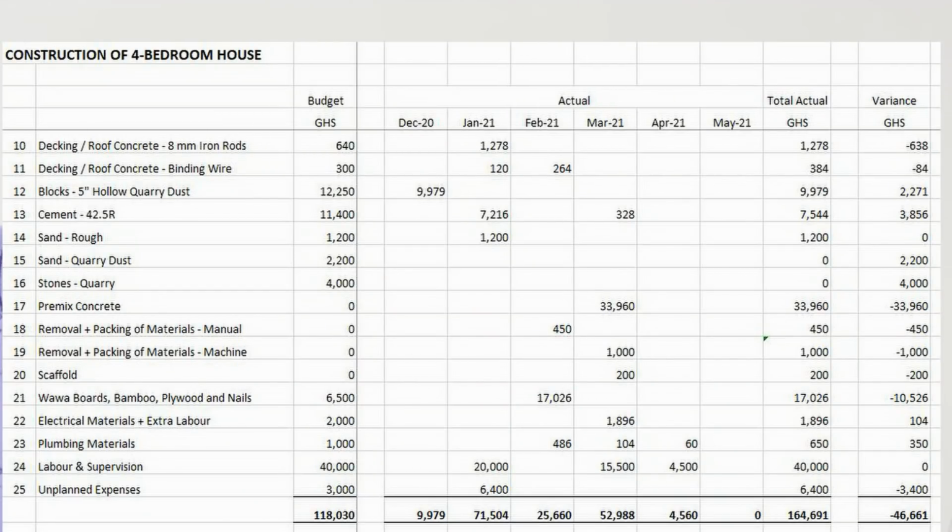So let's look at an example on your screen. I've taken stage C as an example, so let me bring it up on my laptop as we talk through it briefly. We called our stage C the decking of the ground floor, the high level ground floor slab, and the walls from the first floor to the roof. That was our main stage C. You can see on your screen we have a number of items. You have the continuation pillars, which are columns on the lower levels and have to continue all the way to the roof.